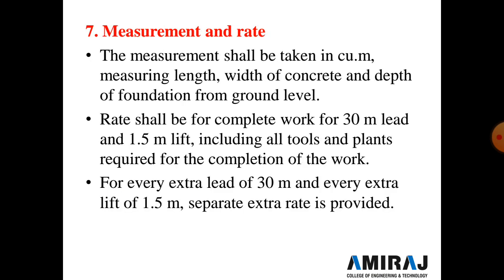Now seventh is measurements and rate. The measurements shall be taken in cubic meter, measuring length, width of the concrete and depth of foundation from the ground level. The rate shall be for complete work of 30 meter lead and 1.5 meter lift, including all the tools and plant required for completion of the work, and for every extra lead of 30 meter and every extra lift of 1.5 meter, a separate extra rate is provided.